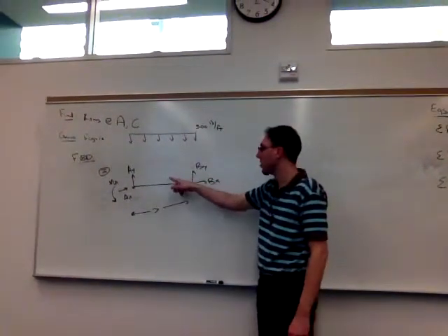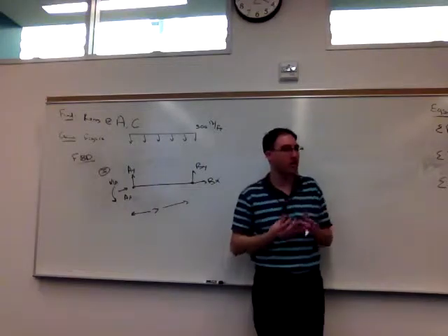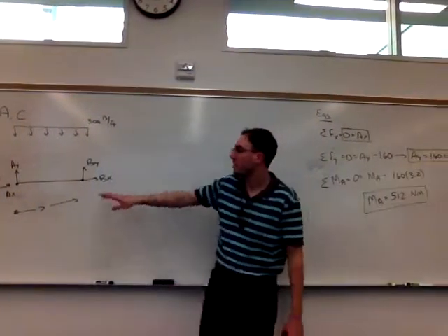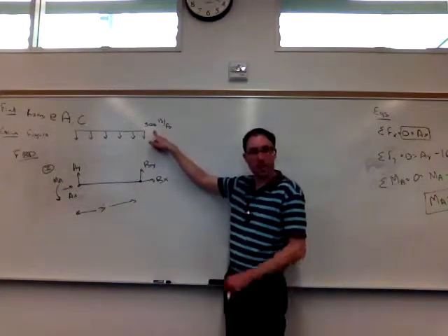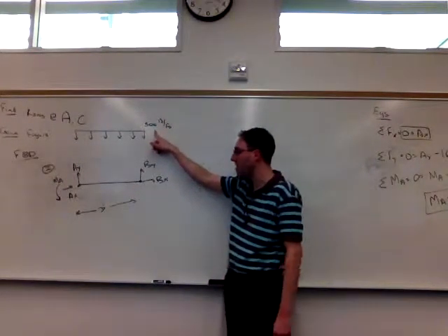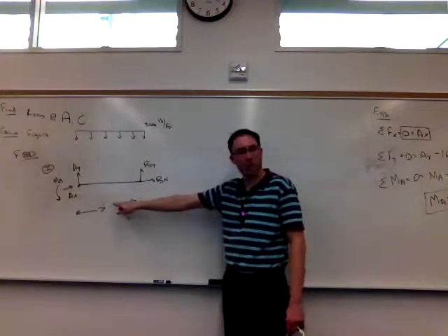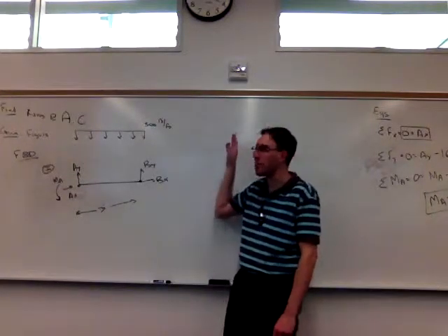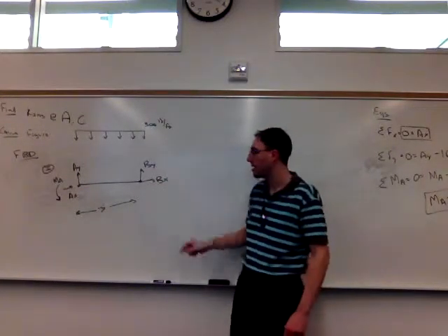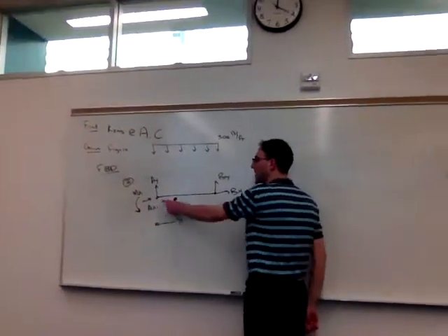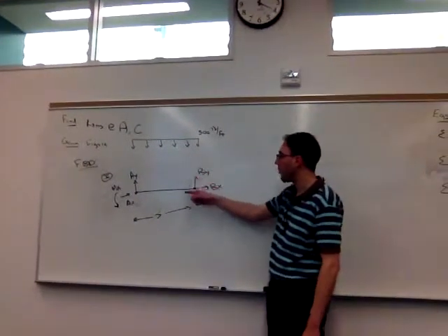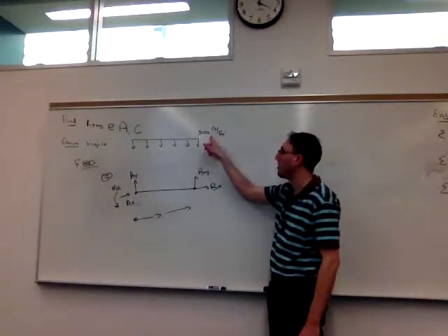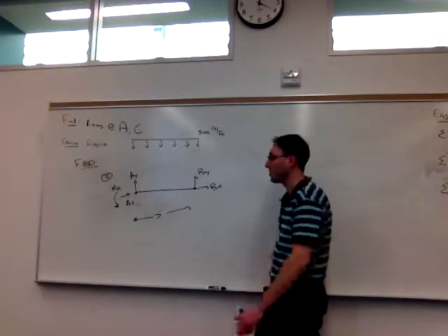but it only knows that this is the distributed load that's acting on it. So for this picture, the only external force that will be acting is from this amount of the distributed load. So the constant intensity of 500 pounds per foot over only 3 feet, even though the entire distribution goes over 9 feet. In this picture, only the 3 feet that touch this beam are going to be used. So the equivalent force from just this amount of it will be 500 pounds per foot times 3 feet.